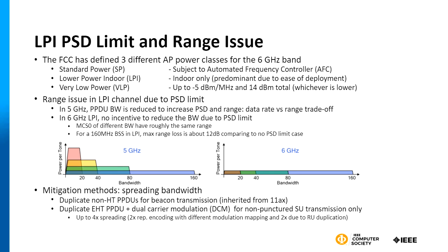Yeah, so from a standards perspective, it's kind of beyond the standards, but experience-wise, your scheduler has to take into account not only the available bandwidth that you have in that particular channel, but also the range that you can achieve, because the higher you go in the band, the lower the range that you can achieve, and also the channel utilization and the particular parameterization that the stations are using.